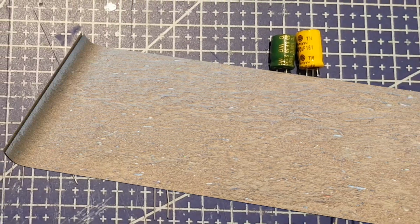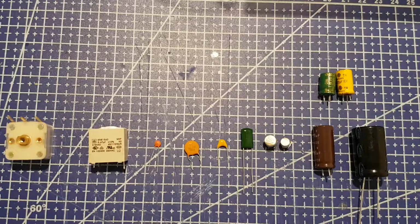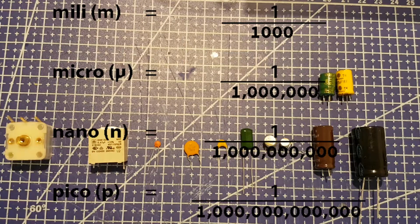That is because they are rolled up into a tube, which increases the surface area while keeping the size small. Now the unit of capacitance is the farad, and it is quite a large unit, so whereas the units of resistance generally go from a magnitude of 1 ohm up to millions, the mega ohm, farads go the other direction and generally start with a magnitude of 1, which is a reasonably big capacitor.